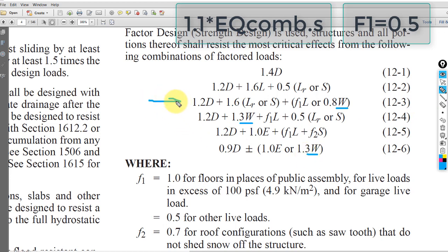Okay. Wind load combinations, as we see in the code, we find wind in these three load combinations. First load combination: 1.2 dead plus 1.6 live for roof. We made this mistake, in this project we didn't assign special live load for roof, but it's very small, so I will ignore it. In other projects we have to assign special live load for roof. We don't have snow, so we will ignore this term.